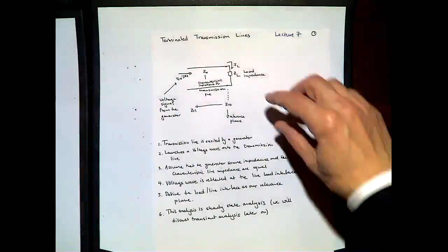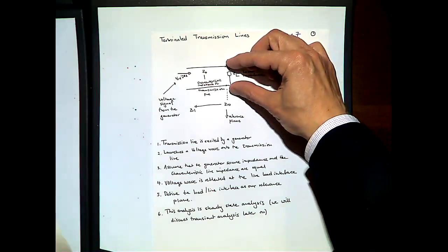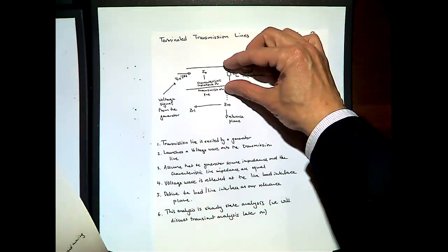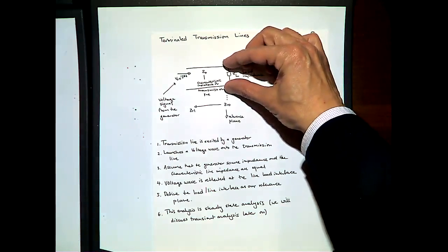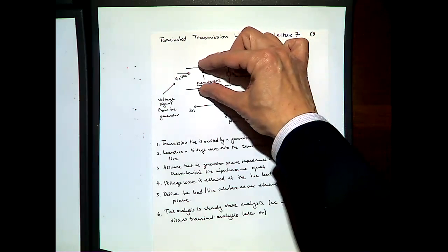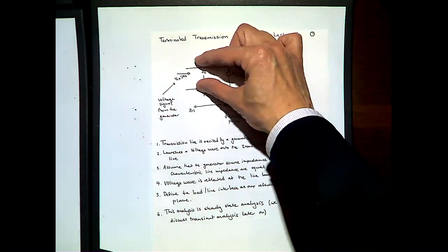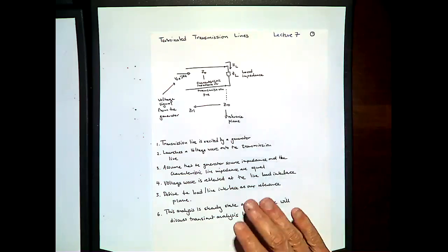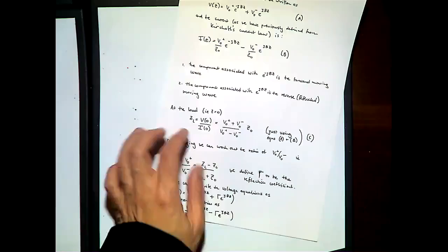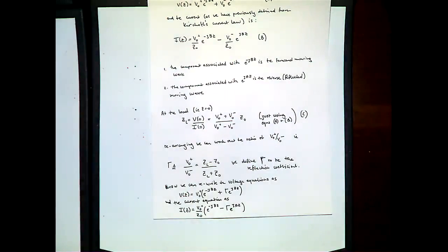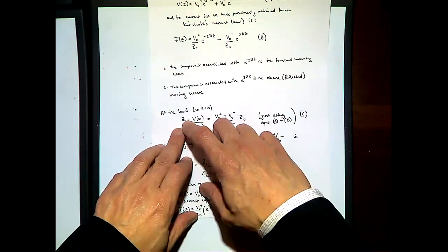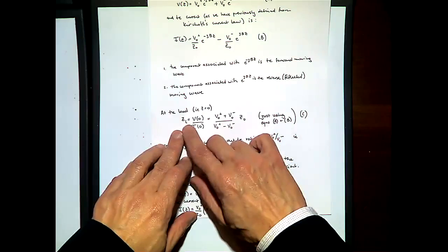So essentially what I'm giving you is what the impedance is going to be at this particular reference plane, and as we increase the length of the transmission line, that is essentially changing the reference plane at which we're looking at and characterising that impedance, which gives us our particular impedance.